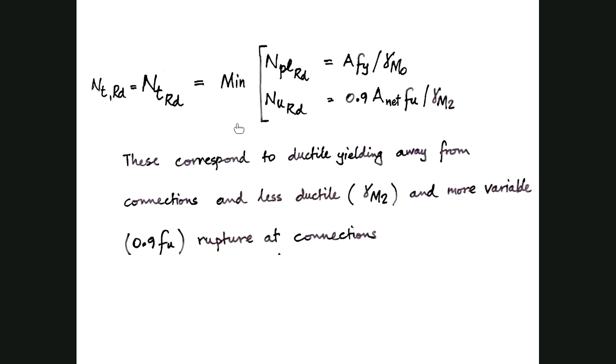So you need to put down that the tensile resistance is the minimum of all those 3 calculations you did, and equals the number, whatever they ended up as. And then at the very bottom, you say NtRd equals, and write out what the number is. Okay, so that was the first thing, that a number of people hadn't done that.